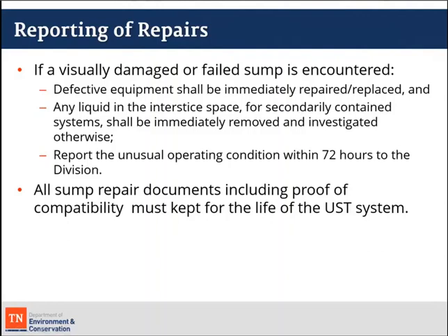So in the case of a secondarily contained system, whether it be a sump or a tank, anything like that, if you're having liquid present in the interstitial space, that must be immediately removed and investigated. In the case of a secondarily contained tank, that is a suspected release, and that should be reported to us within 72 hours.